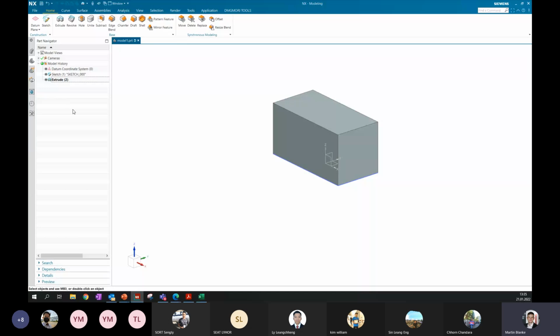Now I would like to know how many bodies I have. So I must switch this view from time step order to body order. How can I do this? I place my mouse over here, then I press the right mouse and this dialog box is invoked. And then you can find this one, time step order. Click with your left mouse on this time step order.